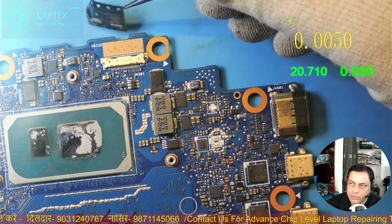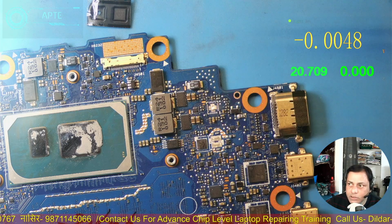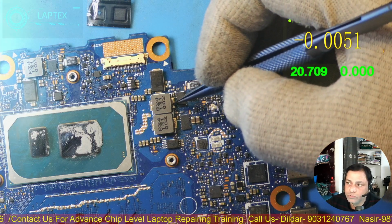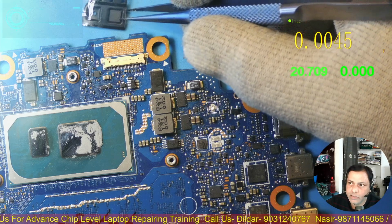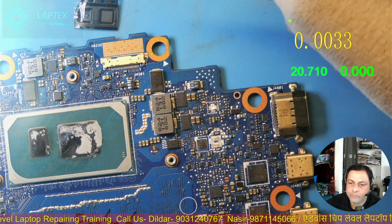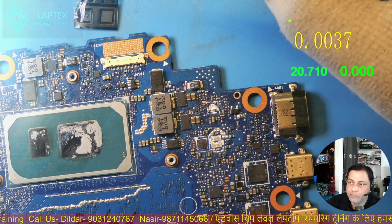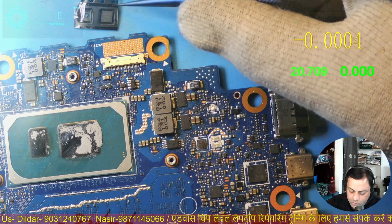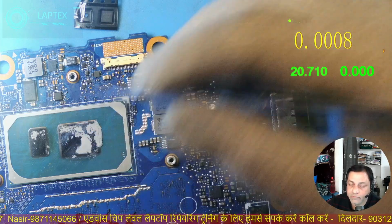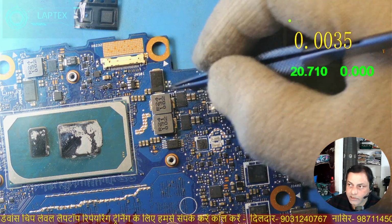If there is a problem in the core IC and you use it, maybe your core voltage will not generate, because it contains a PROM inside the core IC. There is some addressing and some vendor ID specification inside the EPROM, which you have to match across the motherboard. The core IC will communicate with the SIO with the same address, and only then will the core voltage be generated.